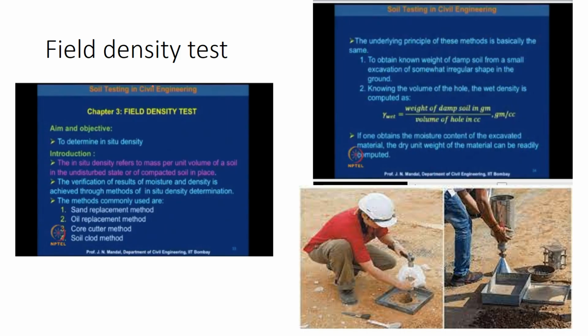Fine. So first we have seen about water content. Next we have seen about specific gravity. Now we go for field density test. You have seen construction of roads, especially they use these compacting rollers, which will be running to and fro, and it will compact the ground. So how do you know that it is compacted? Compaction is a process in soil mechanics where you reduce the voids. To put it in a simpler fashion, I can tell.